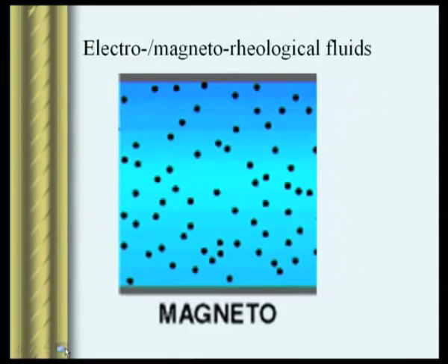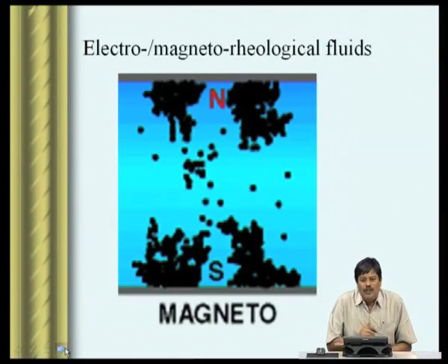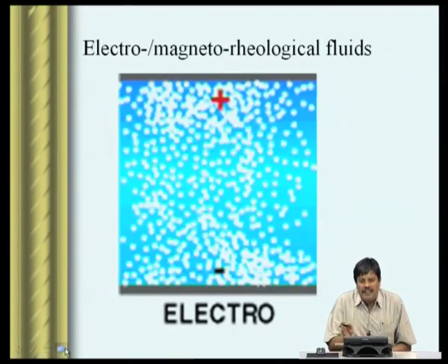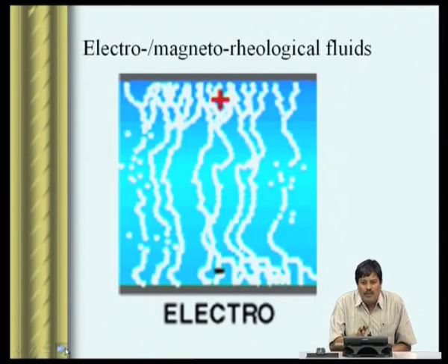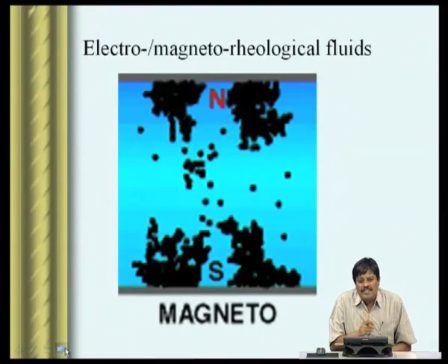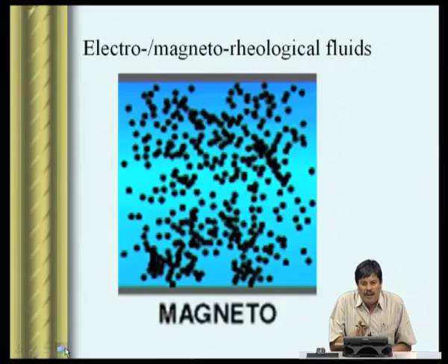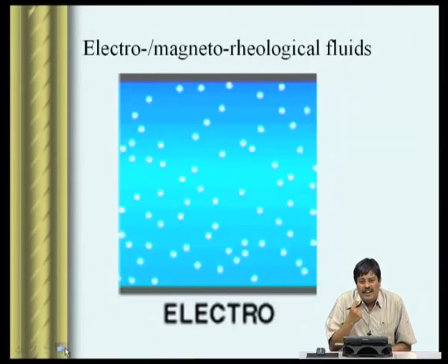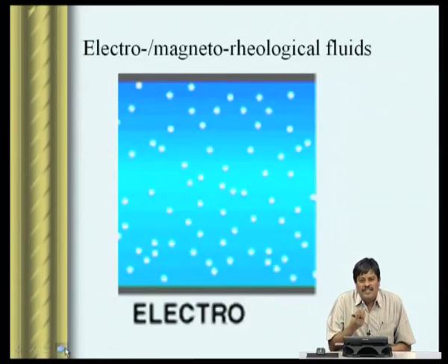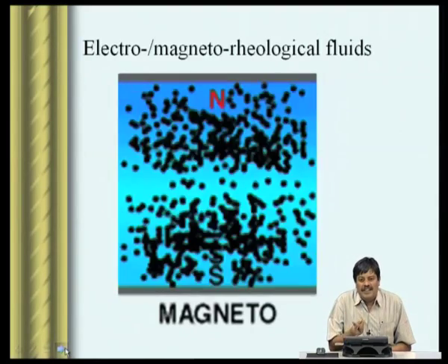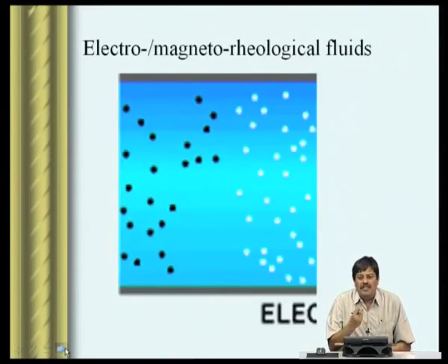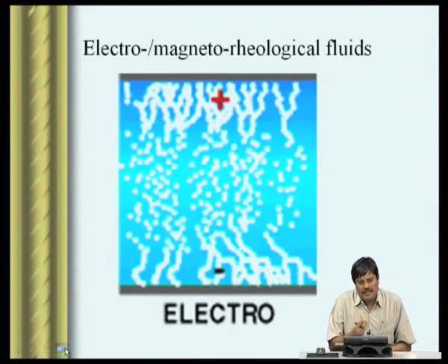So, you could see in this video how the magneto-rheological material, which was arbitrarily arranged, gets oriented due to the application of the field. This clearly shows that by this process a fully liquid becomes a semi-solid material. So, basically it is a smart material that can change the viscosity, thereby it can be used for applications involving damping of the structure.